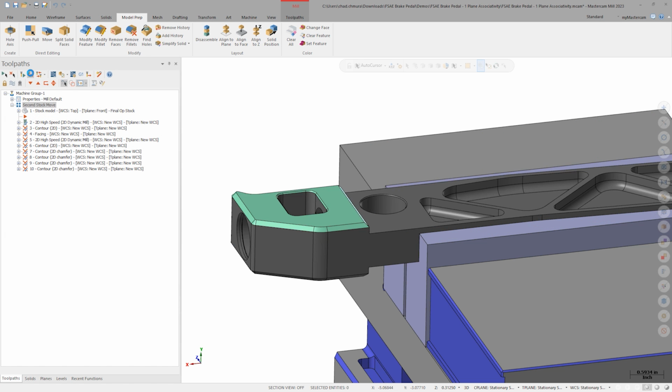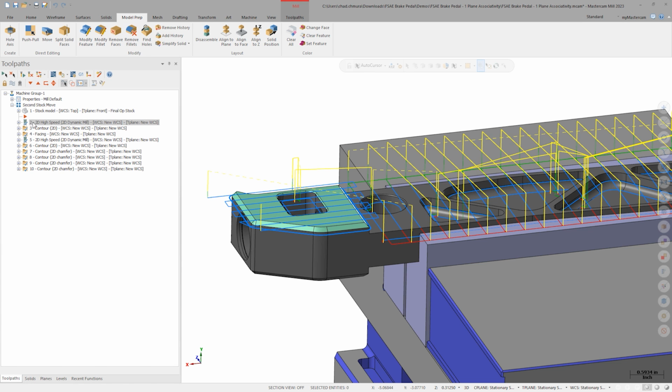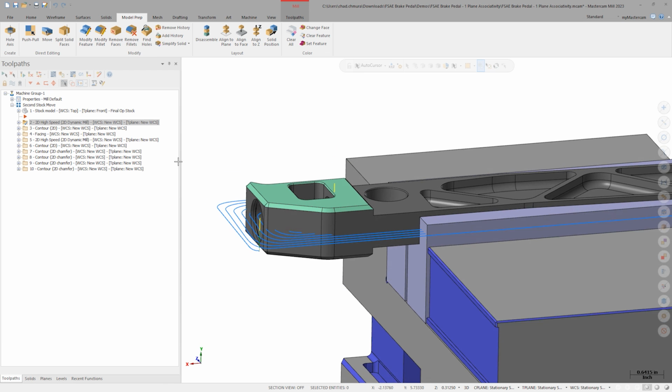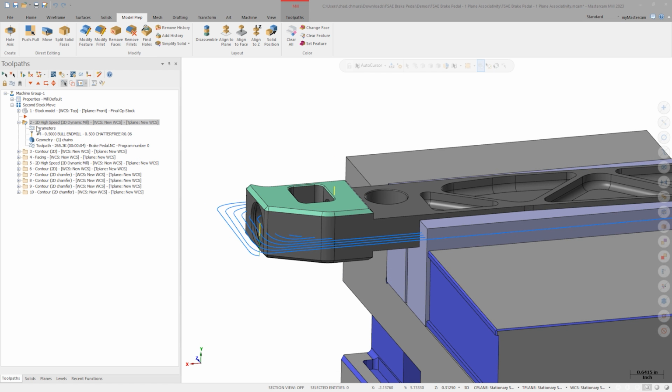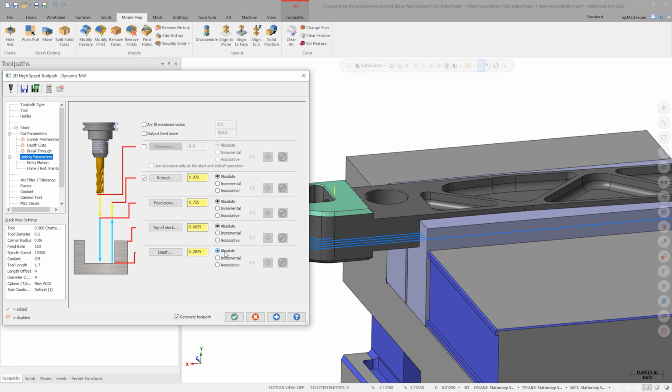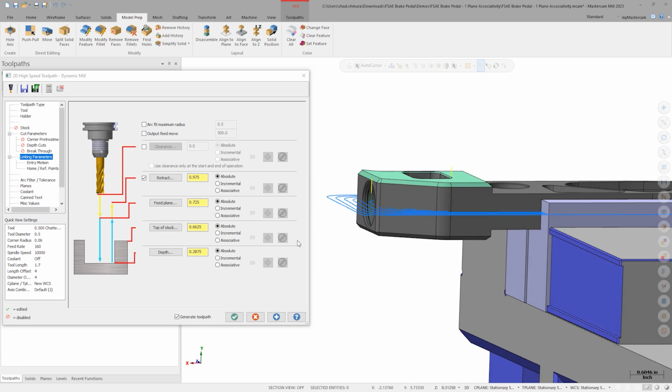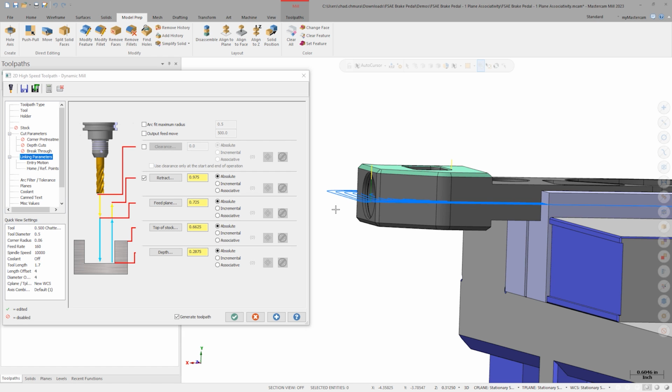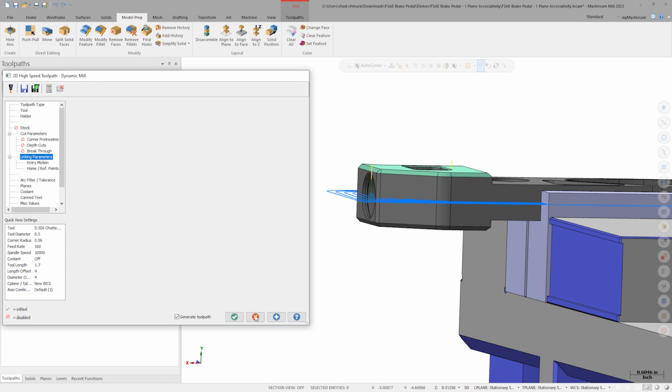We see that most of the operations are ready to run with their new work offset. Yet there's a problem with operation 2. Open the linking parameters page for this operation. Note how all the values are set to absolute. We measure absolute value coordinates relative to the work offset origin. By relocating the work offset origin lower in the Z direction, this cut has shifted lower.